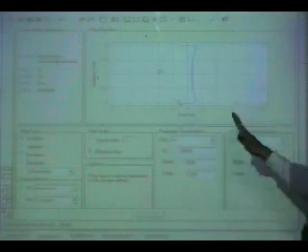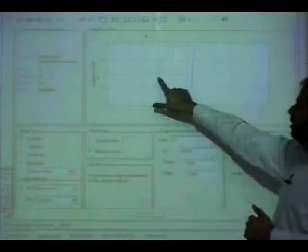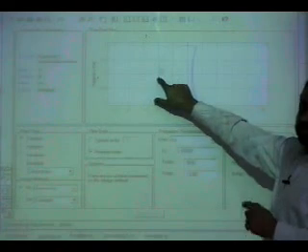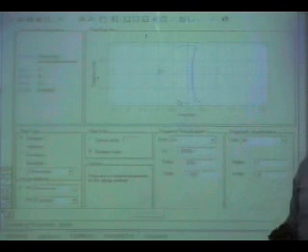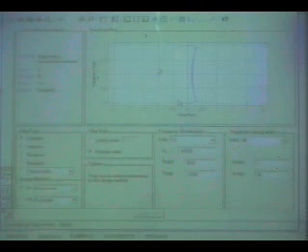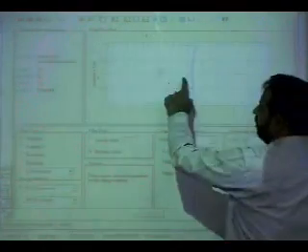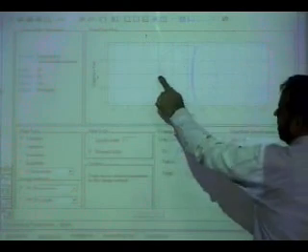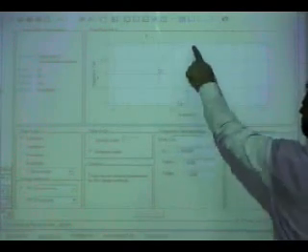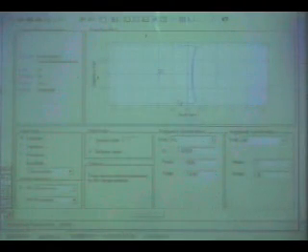So these are now on here, and they are 31. Remember the zero which was at 1 plus z inverse. For every pole there is a zero at 1 plus z inverse. So if you count, there are 31 of these here. So every pole has a zero here, 1 plus z inverse. Okay, so 31 zeros here, and all this is the other poles.